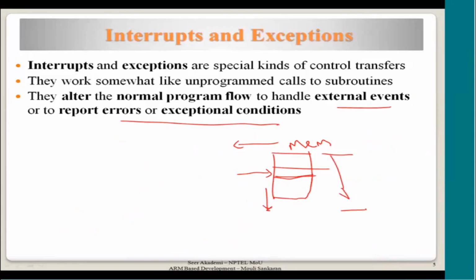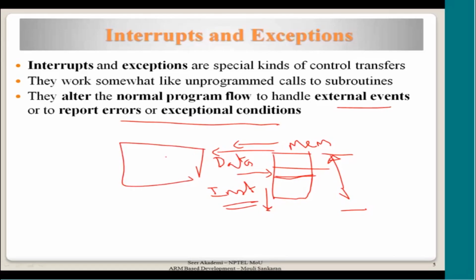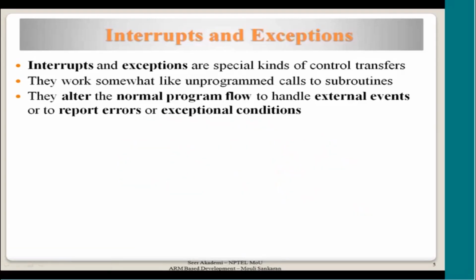It depends on the hardware, how memory is configured, and to which address it is mapped. The memory system may respond back saying that there is a problem while accessing data, or while accessing an instruction. Based on this, a specific input will be given to the processor, and the processor responds back by executing the handler. That is what are called exceptional conditions. Let us see more of this.